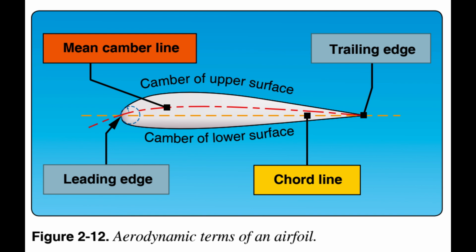3. Relative wind, defined as the airflow relative to an airfoil, is created by movement of an airfoil through the air. This is rotational relative wind for rotary wing aircraft and is covered in detail later. As an induced airflow may modify flight path velocity, relative wind experienced by the airfoil may not be exactly opposite its direction of travel.